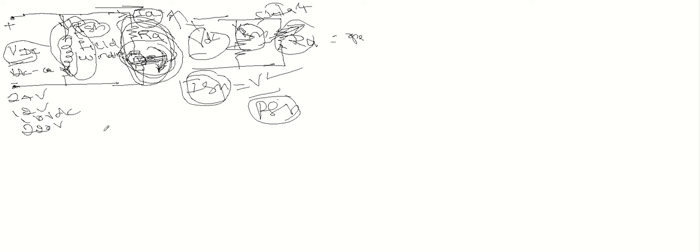And you know that in this case the flux is proportional to ISH, that is the current flowing through the field winding. Since this ISH is constant, throughout this entire operation the flux is going to remain constant.